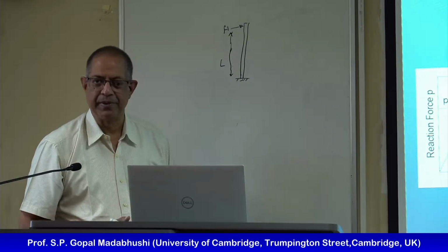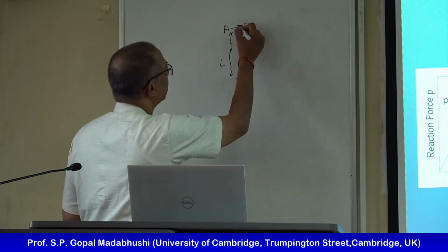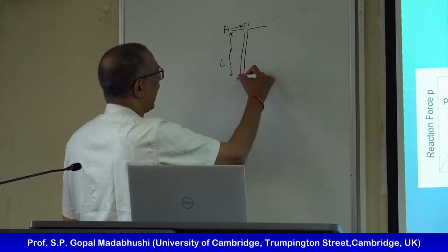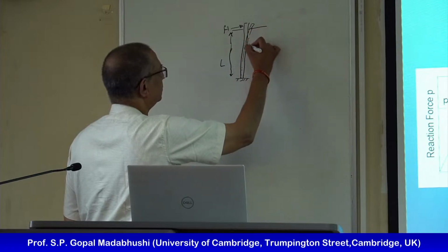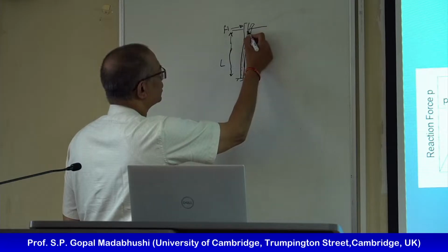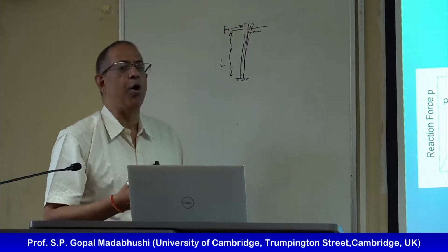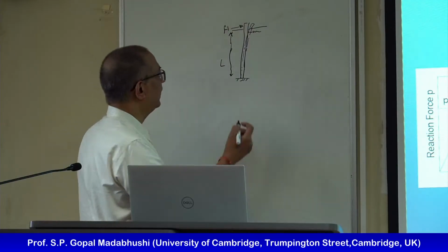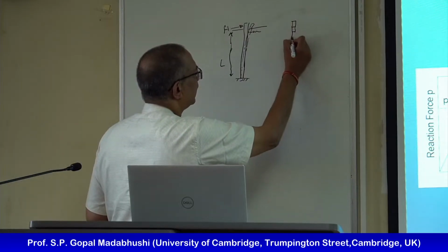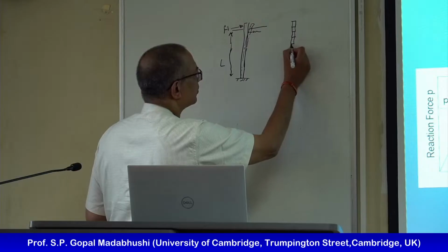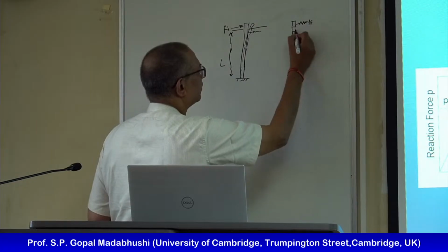That is easy. Now, obviously, piles are not sitting in air, they are sitting in soil. So as the pile wants to deflect like this, it will be opposed by the soil. One way to see how much resistance I get is by imagining my pile is made out of lots of elements, and each of them has a horizontal spring.